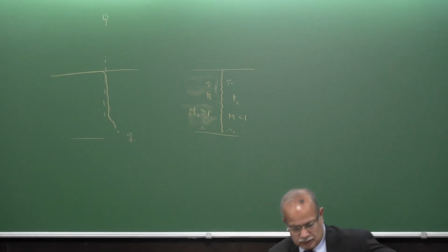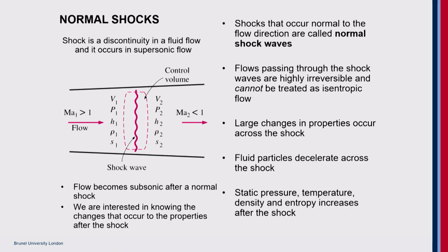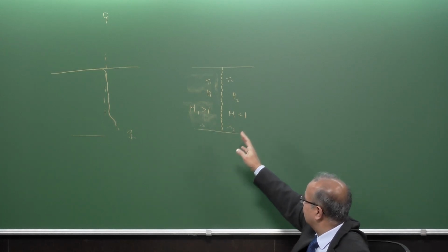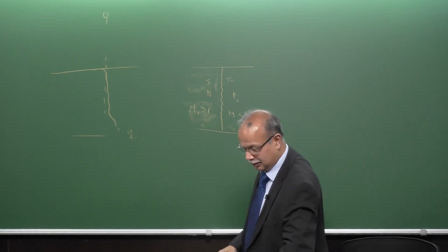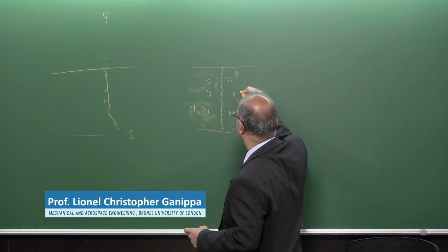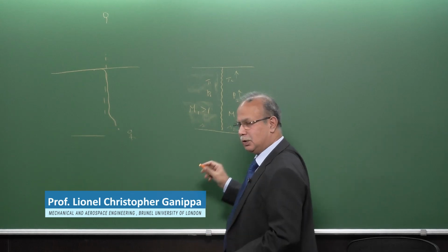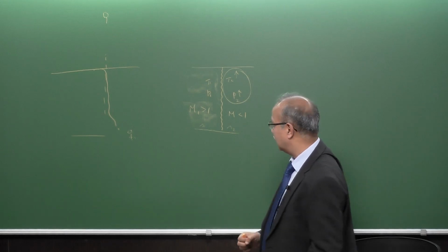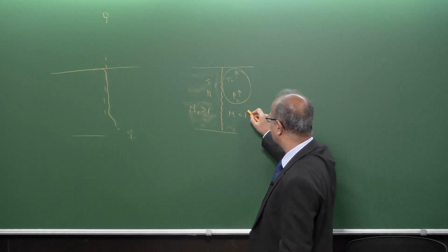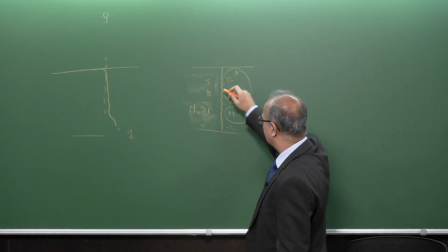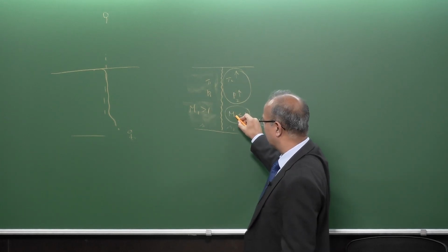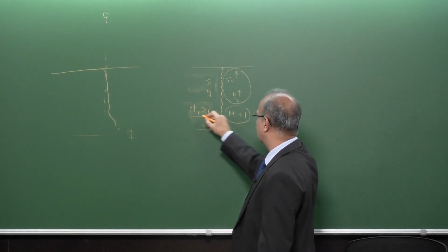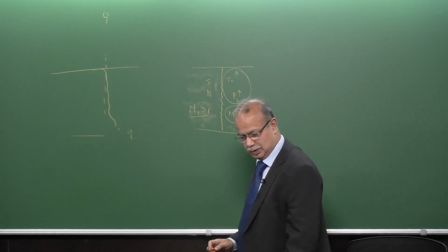All of the properties change. So after this spontaneous jump, you have an increase in temperature and an increase in pressure. We are going to make use of this advantage in aircraft applications under supersonic speeds. But we're also going to see how you could use shock waves to decelerate the flow. A strong deceleration, coming from high supersonic, immediately it becomes subsonic.